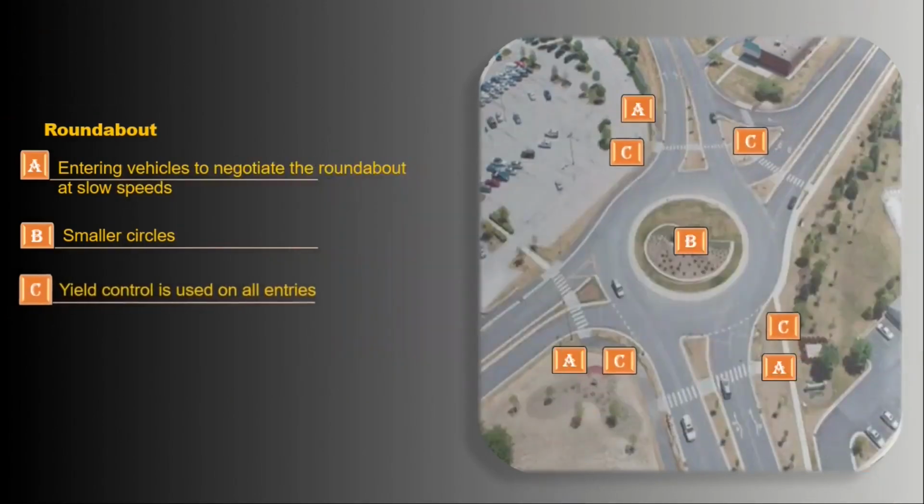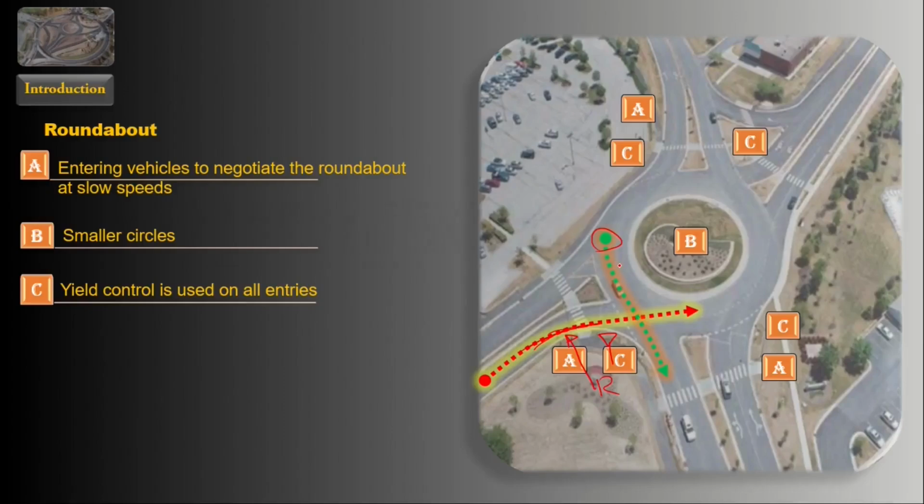All right. Again, unlike the rotaries, entering traffic must give priority to circulating traffic. It's a rule, and also it's induced by the geometry of the roundabout. But how? As we mentioned a few minutes ago, due to this deflection, entering speed is controlled and consistent with the circulating speed, which means that they're operating at almost the